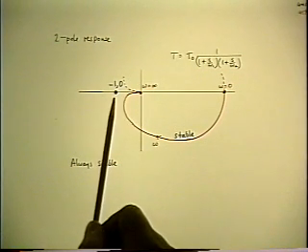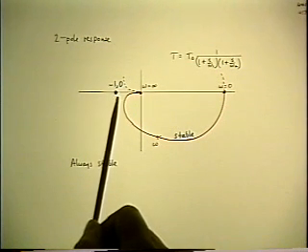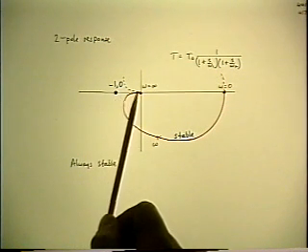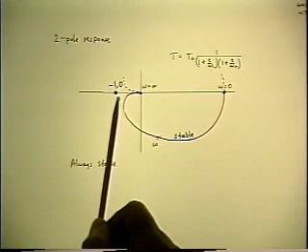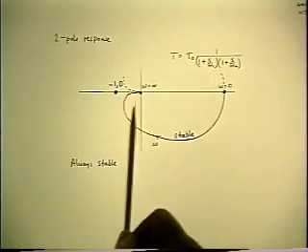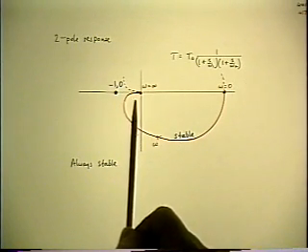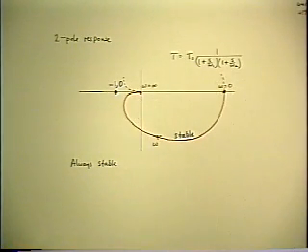It could get very close to it, but it will never get to the -1 point, because that would require the magnitude to be finite and the phase angle to be 180, but with two poles you don't get to 180 until infinite frequency when the magnitude is zero. So still, a two-pole loop gain is always stable.